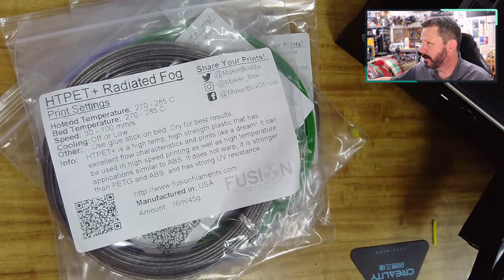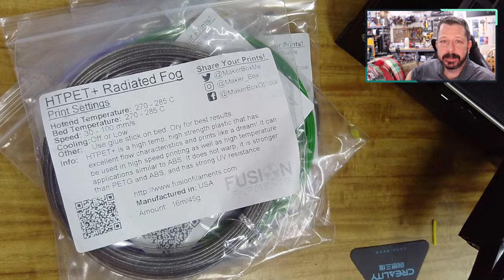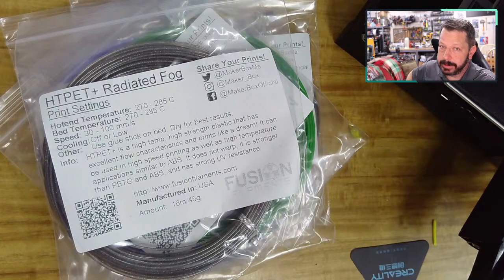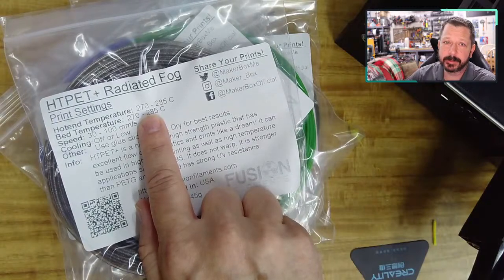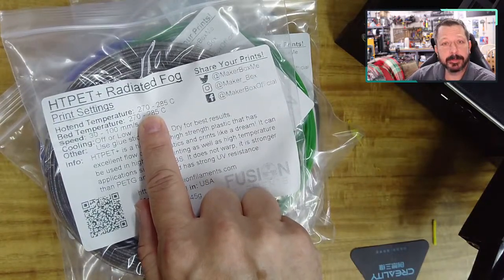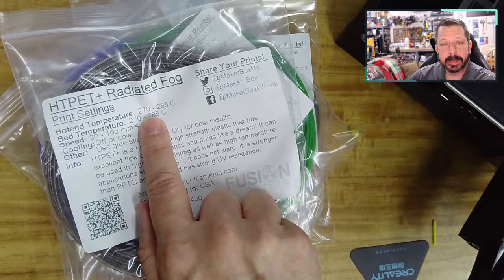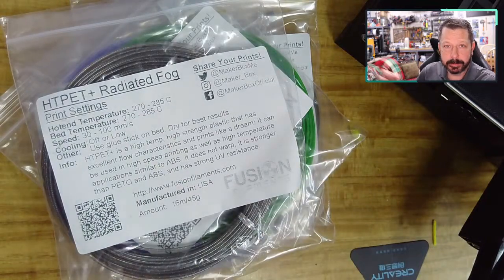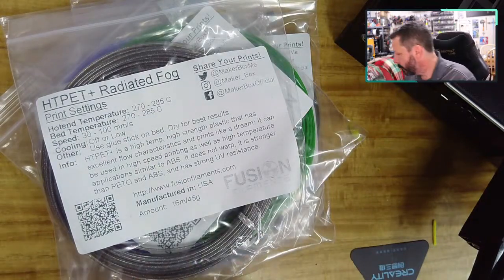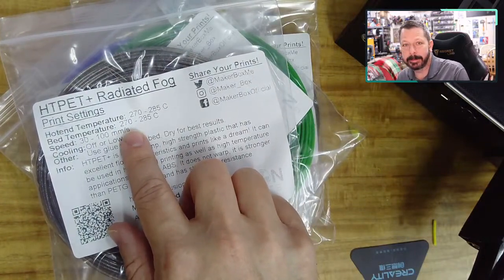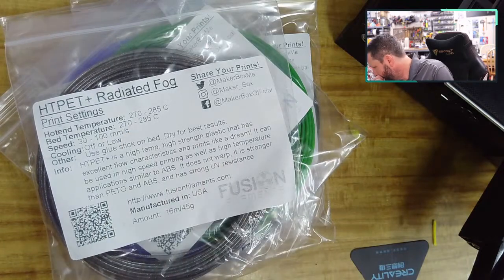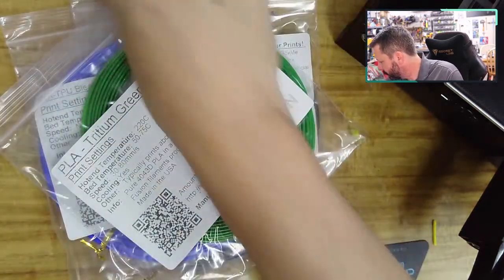The tube itself is Teflon, and Teflon begins to break down at around 250 Celsius. So if it's getting heated to 270 Celsius, that's going to be a problem. They do make printers with all-metal hot ends where the tube stops short of the heat, and that's okay. But you still couldn't get the bed up this high. There's no way an Ender is going to get its bed that high without serious modifications. So we'll throw that one to the side.